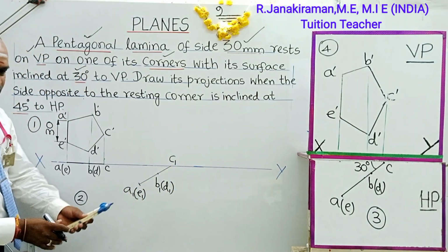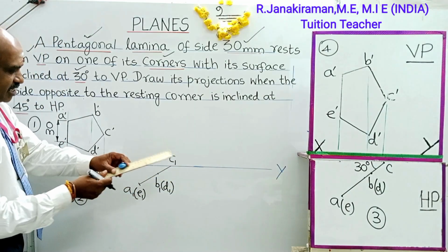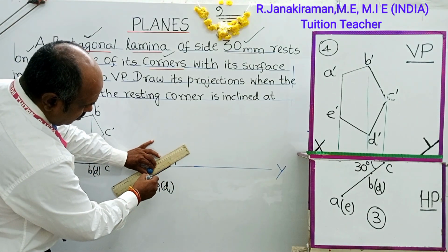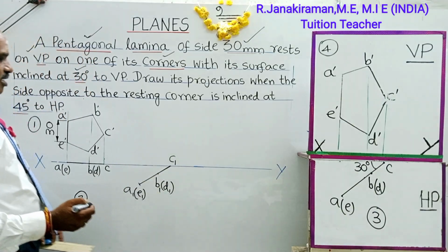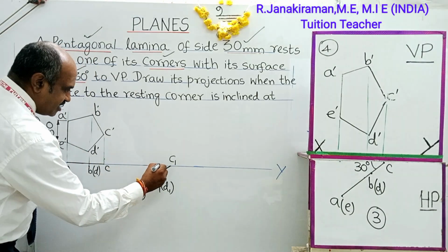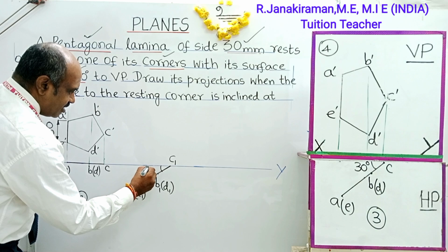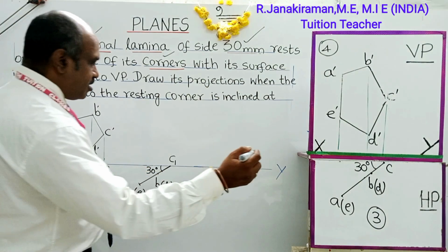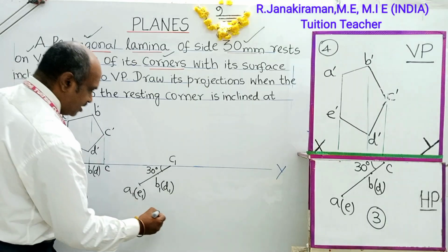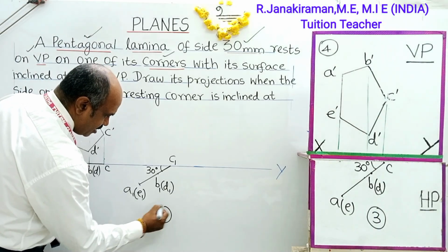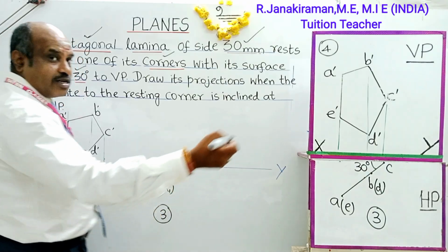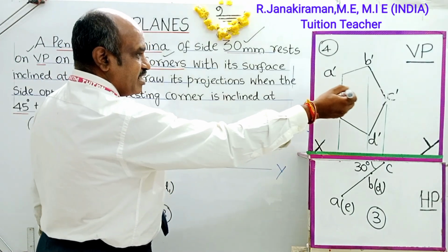Join C and E, A, by H or HB pencil, as it is an object line, a visible line. Okay, so this is the surface inclination angle, given as 30 degrees. Understand? Next I go to draw the fourth diagram. This was our third diagram completed. The fourth diagram, I'm going to draw the front view, the surface inclination front view.